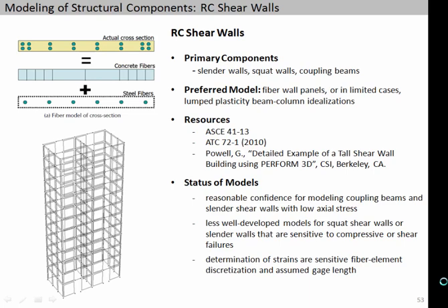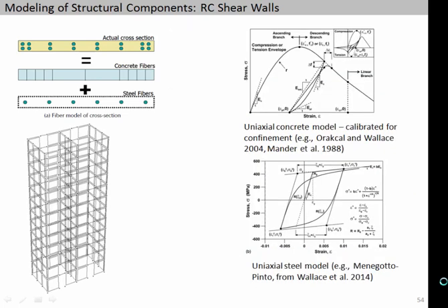Typically we model the shear behavior as being elastic, so that means that's going to be our force controlled component. And again, you see some of the references that are shown there. There are a number of models out there to model the uniaxial concrete behavior in tension and compression. Tension we will discount a lot of that, but the compression models account for confinement.